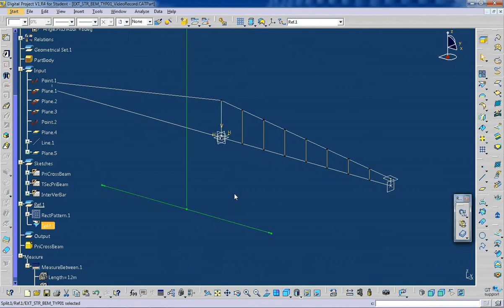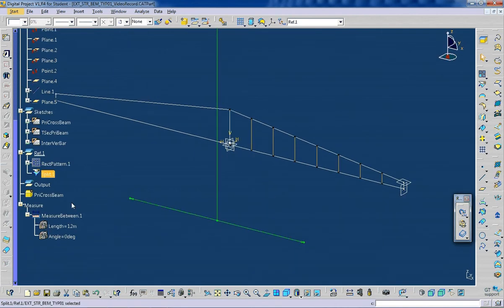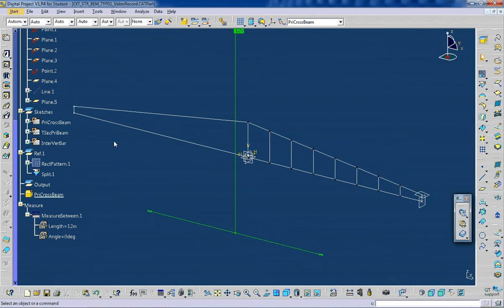Alright, so okay, let's do this crossing beam. There's one tip for this part. If you have something you want to do as symmetric, do the symmetric first and then do the other bit afterwards. Otherwise it will put everything as mirror and create some redundant geometry. Because I'm gonna make this split mirror symmetric to this central plane, I will do that part first.